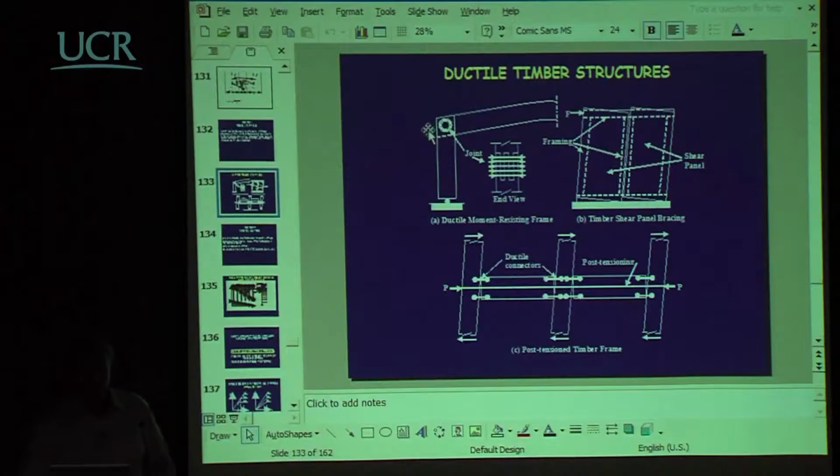And the brief chapter considers three different types of timber structural systems. Of course, we recognize that timber is not a ductile material. It's very brittle. So any ductility in the structure itself doesn't come from the timber. It comes from the connections between elements itself. So here's one example, perhaps glue laminated beam and column connected by a ring of bolts which go through them to connect them, and those bolts actually crush the timber on either sides of the bolts itself, creating some inelastic action without fracturing the elements.